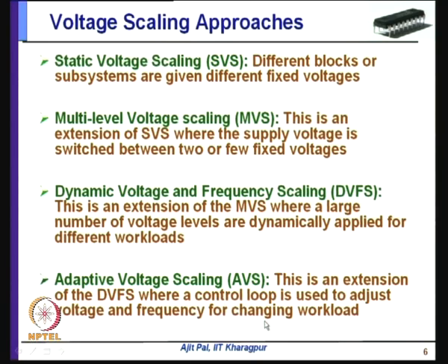So, you have an additional hardware which finds out the voltage and frequency to be used in this circuit. So, adaptive voltage scaling techniques require additional hardware to find out the voltage and frequency, however, it gives you much better performance, much reduction in power dissipation, because it is done at run time.